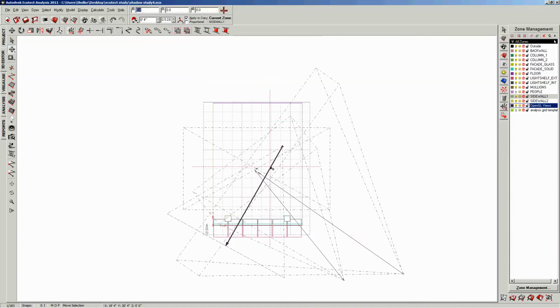Okay, so now if I move it, it's actually a copy of it. And I want it to look straight onto the facade. I think that's a more analytical view. It's easier to read the contour. So I double clicked on it so I could get the grab bars, and I made it so that we could look straight at the wall. I'm going to also move it into the center, which is here.